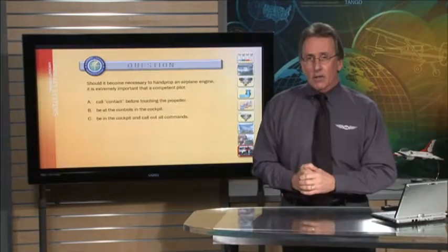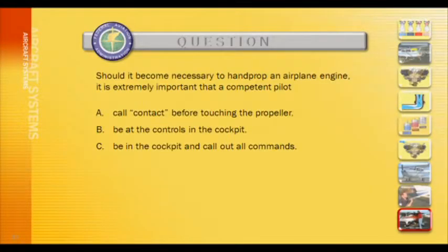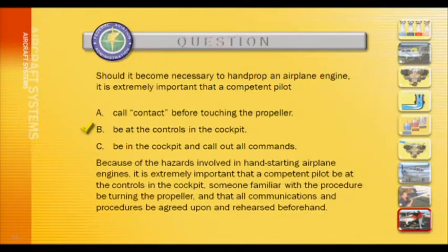Well, have you got the answer? Certainly hope so. Should it become necessary to hand prop an airplane engine, it is extremely important that a competent pilot be at the controls in the cockpit. Again, a reminder, because of the hazards involved in hand starting airplane engines, it is extremely important that a competent pilot be at the controls in the cockpit and that someone familiar with the procedure be turning the propeller, and finally that all communications and procedures be agreed upon and rehearsed beforehand.